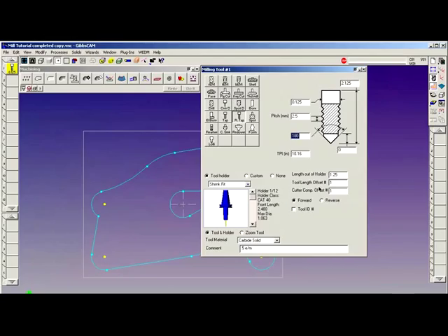The default angle at the bottom of the tap is 180, assuming a plug style flat bottom tap. Mentioned threads per inch, and this is the length of the lead on the tap. Spot face, overall length, diameter, corner radius if any, number of flutes. Pretty self-explanatory. A reamer is even easier. It's the same definition: overall length, diameter, number of flutes, and the length of the lead or the non-cutting portion of the reamer.